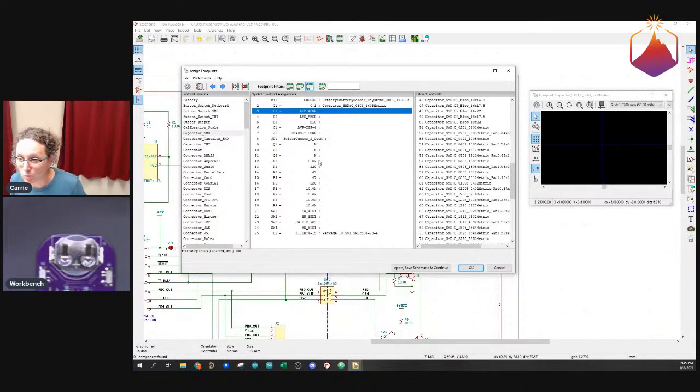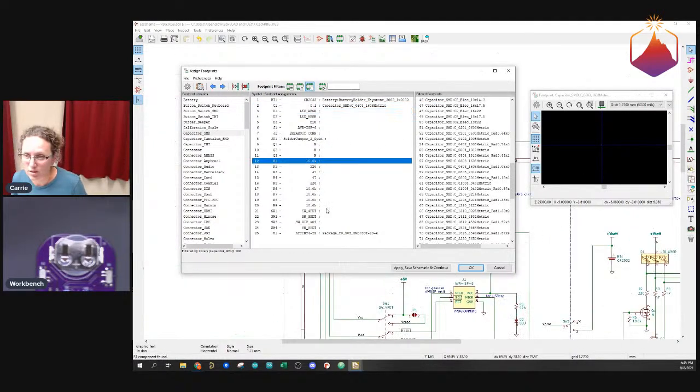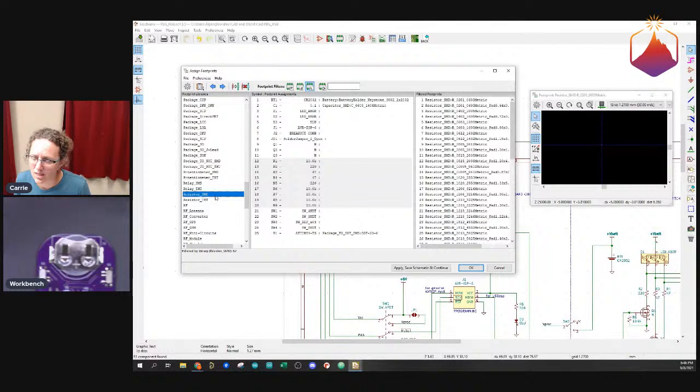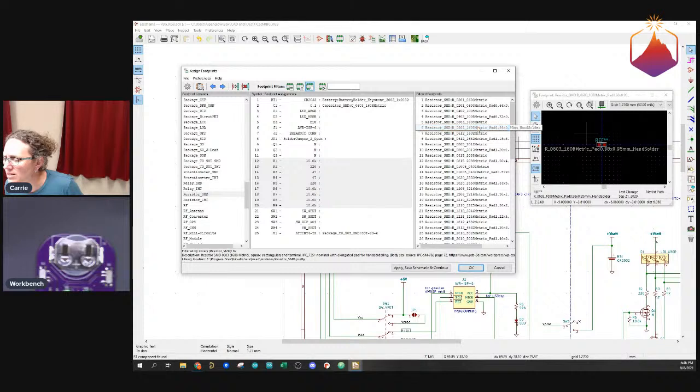Now, let's see. And the resistors are also going to be 0603s. I'm guessing that they probably actually have a different resistor 0603 pattern, which some people do. I use the same footprint for resistors and capacitors because I'm just that way. I don't find it to be very different. So interesting, I feel like this is a little bit smaller than the capacitor one.